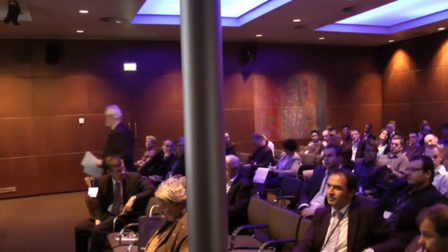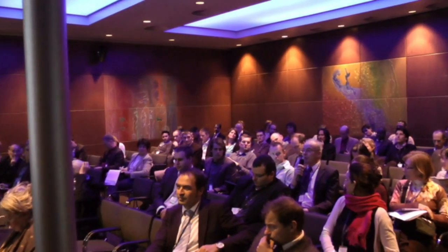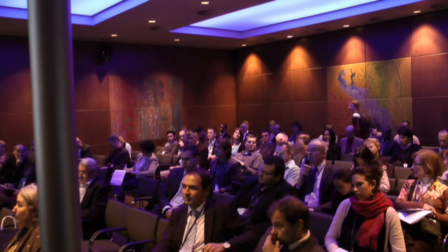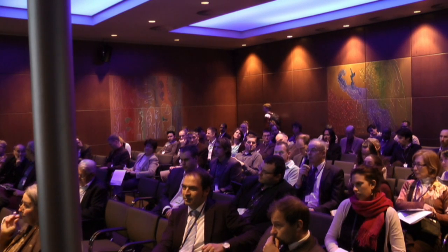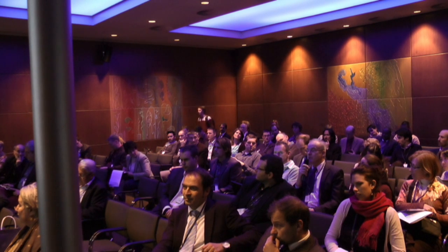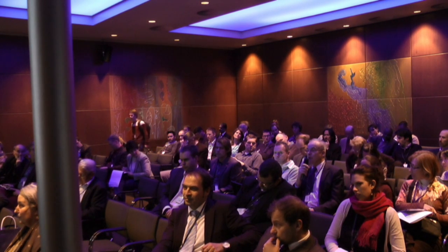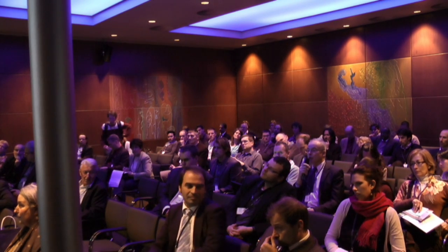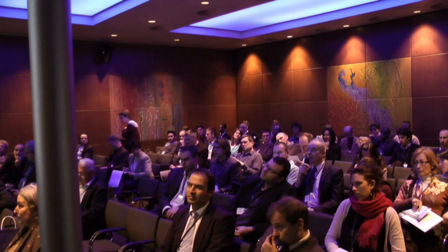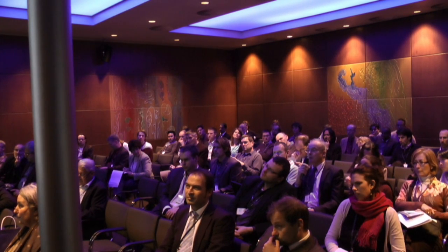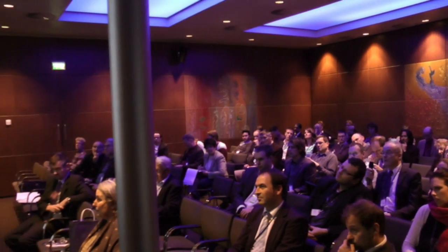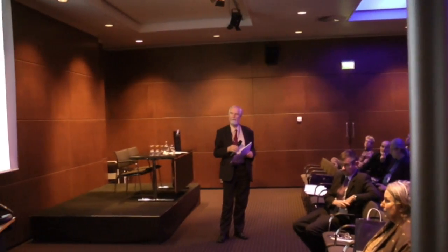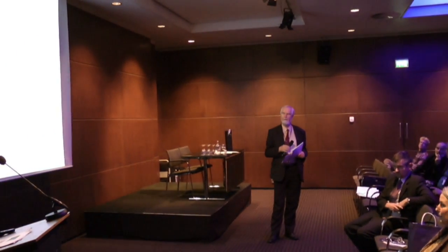I'm Gerard Beaufort, former Rijkswaterstaat. It struck me that the dike base does not erode at all. From Holland's experience, we know that large gaps in dikes exist after a breach, especially in the underground. Have you considered that possibility as well? Erosion of the underground of the dike base has not been considered. No, it has not been considered because we don't consider it to be a massive impact on the hydrograph shape. It does occur, but it's not a factor or parameter we consider to be of massive interest.